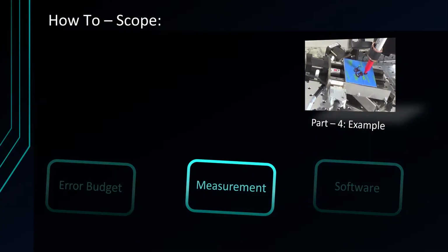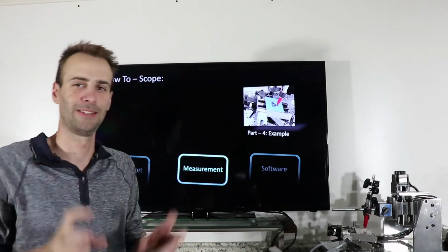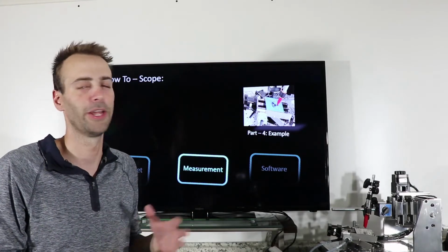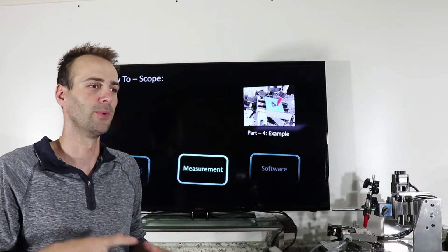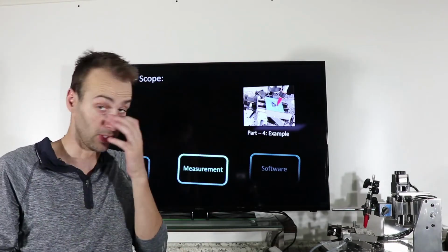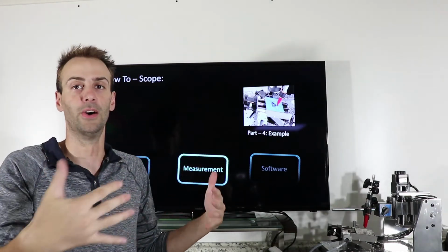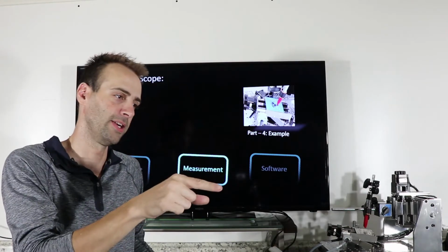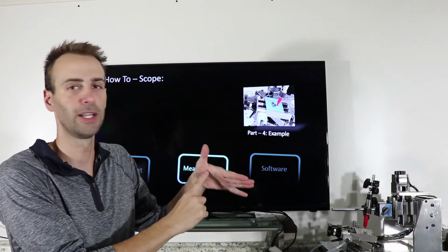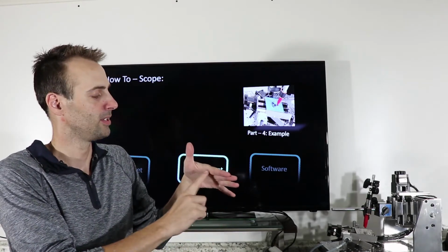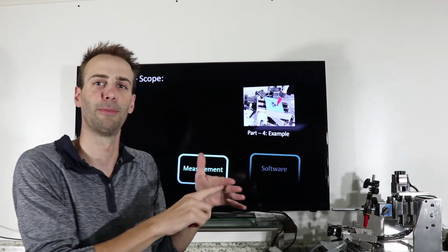You would think that the bulk of this video should be me showing you how to tram and specifically how to measure and measurement techniques, but I think there are enough videos out there on how to measure things. One example is tramming a vise on a mill, okay? So is my jaw perfectly straight? No. But when I put my dial indicator in the spindle and then tram along the vise jaw, it's going to come in and out and follow all the stuff, like, oh, there was a dent in my vise jaw that I picked up on my dial indicator, right?